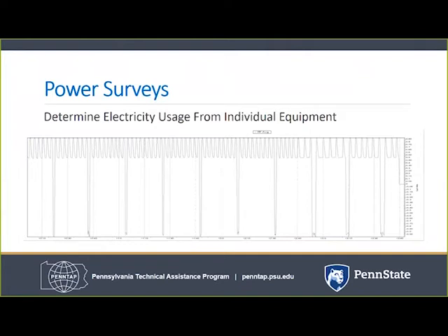Air leaks, for example, may become apparent when compressors continue to cycle on and off when production is halted over a weekend. Power logging data can also help identify sources of peak loads. These may only last for a short period of time, but can represent a significant portion of the overall energy cost for a facility. The detailed demand profile provided by power logs can also provide insights into the main benefits of a renewable energy installation.